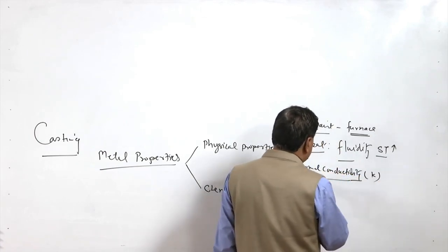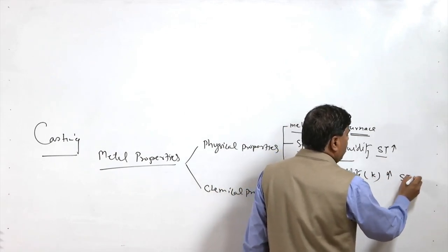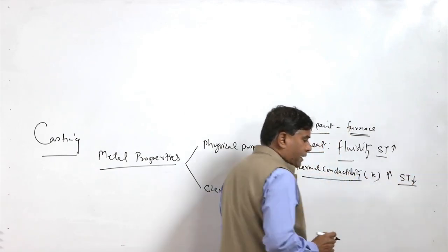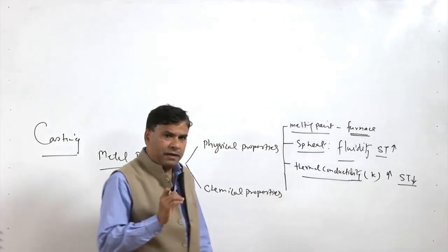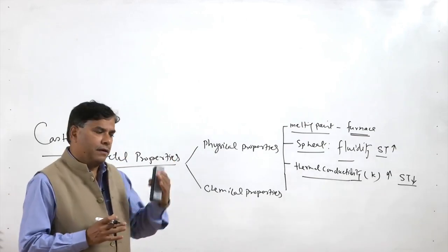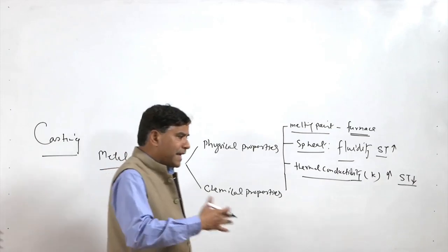In this case, when the thermal conductivity is high, the solidification time will be low, and if the solidification time is limited, then of course it will increase productivity by reducing the casting cycle time.